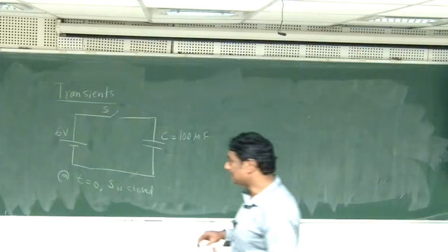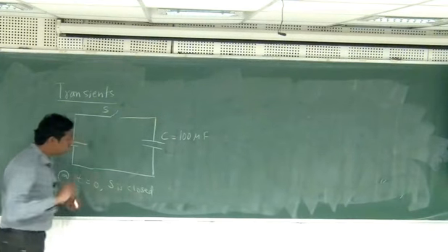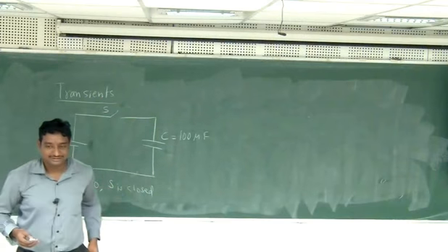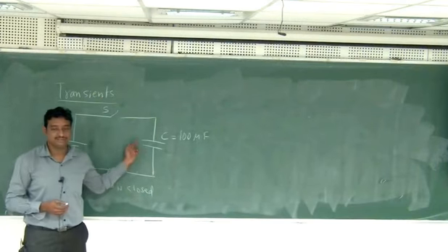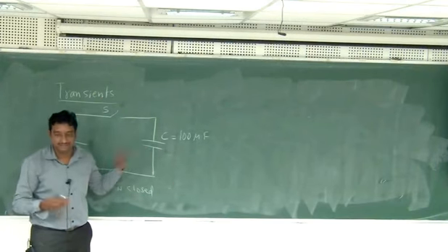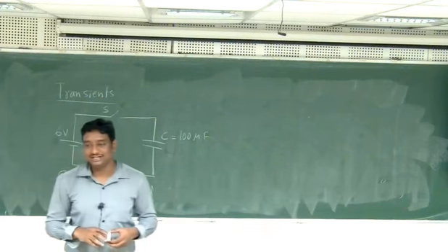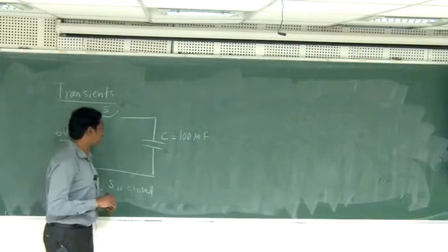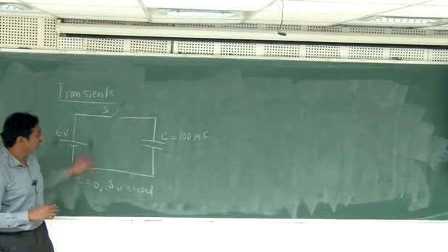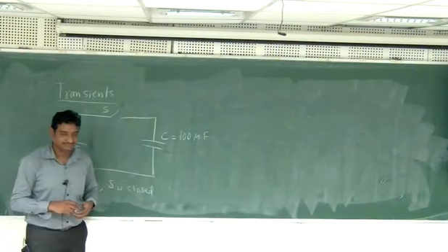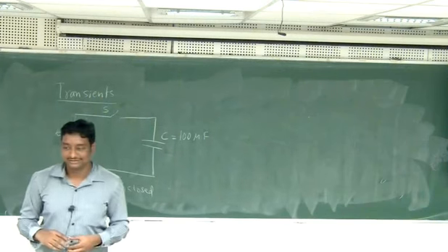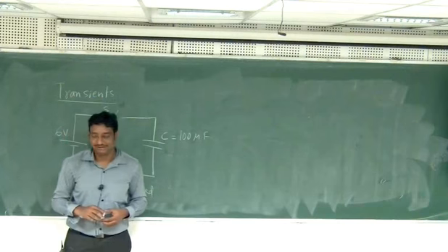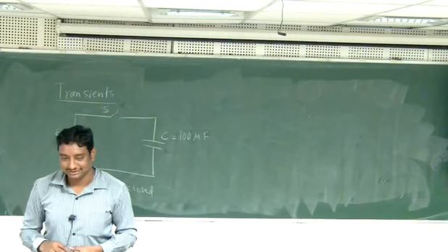Okay. So the answer I heard was, first of all, if I close the switch, is the circuit complete? Is it a closed circuit? But if you see a capacitor, there are two plates with insulating material in between. That's what a capacitor is. Can you still count it as a closed circuit? The answer is yes, you are saying. Then what happens? Will there be a current flow? And how much current? Very large current. Why very large current? Because there is no resistance.